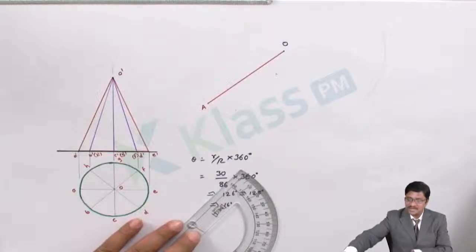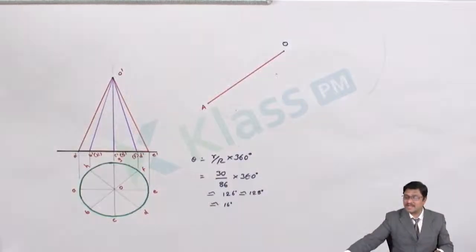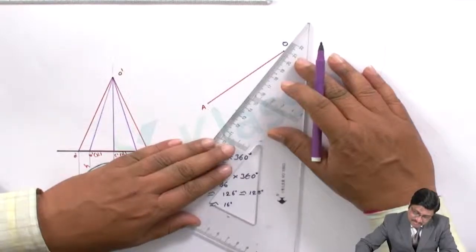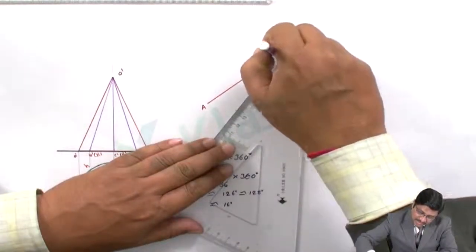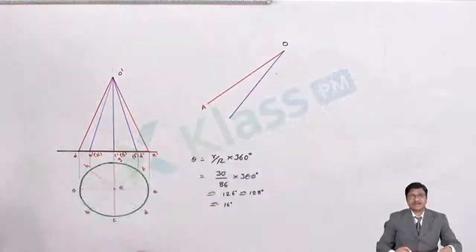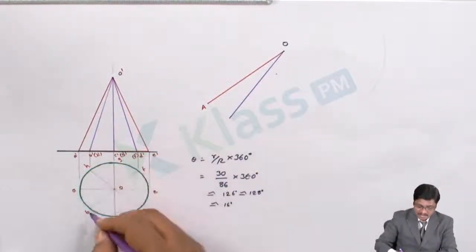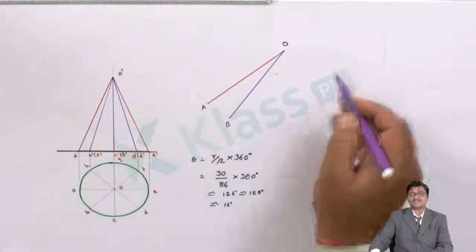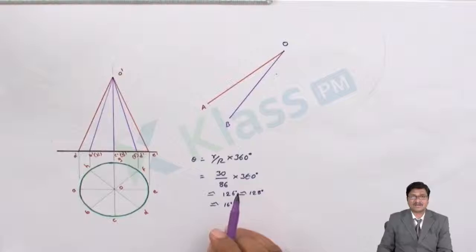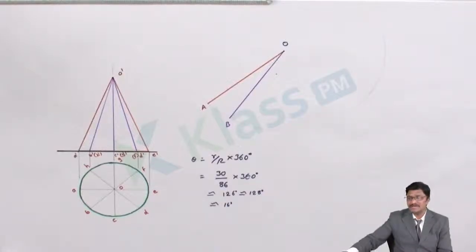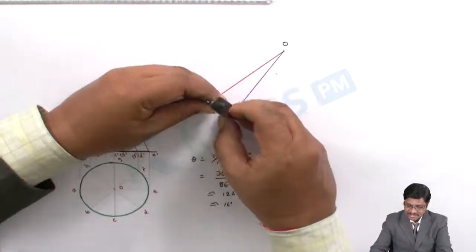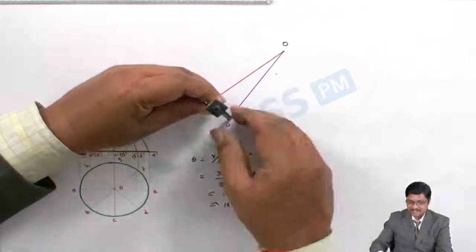For that, I am taking the scale in the direction of the radial division point. Clear? I am drawing a line. I drew a line here. Once completed, this is the next division point B. We know that each division must have the same offset along the curved surface, so that automatically gives the true measurement. Now I will take the compass. Since this distance is the span of 16 degrees, measure linearly this much.